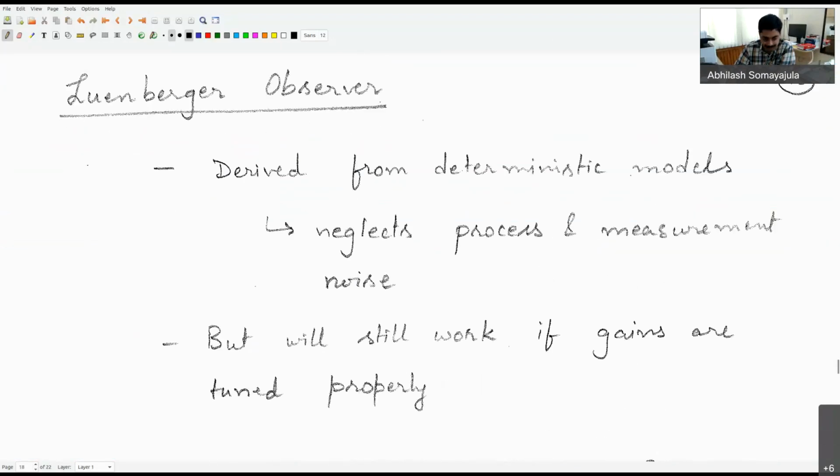That being said, we will now come back to the idea of observability that we have discussed. Now, assuming that a system is observable, how do I design the so-called state estimators which can separate out my low frequency and wave frequency components? Let's take a look at it, and we'll try to apply this to the so-called autopilot systems for our ships, so that it will become a little more clear.